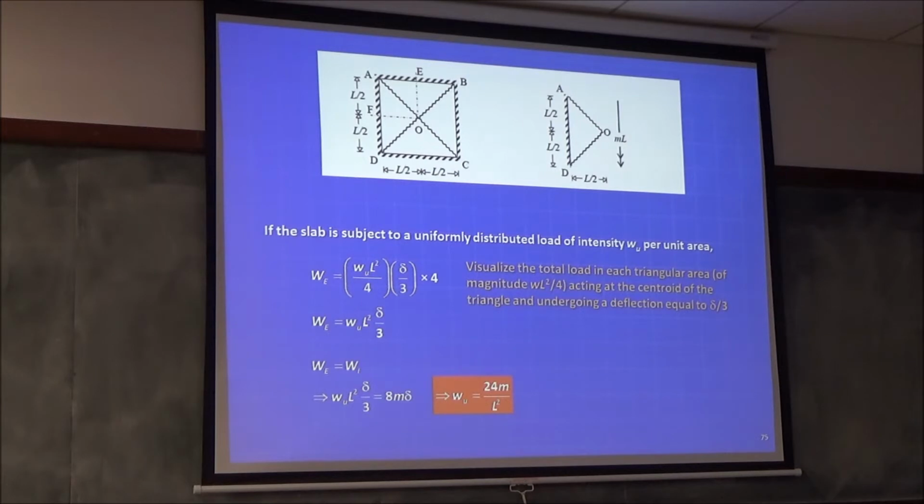So you would expect two-way to be half, 1/6, but it's much more. It's 1/3. It's a little surprising, but that's what it comes to. And actually when you test it, it'll be even more because of the tensile membrane action. Got it? Understood? Very easy. So square slab is child's play.